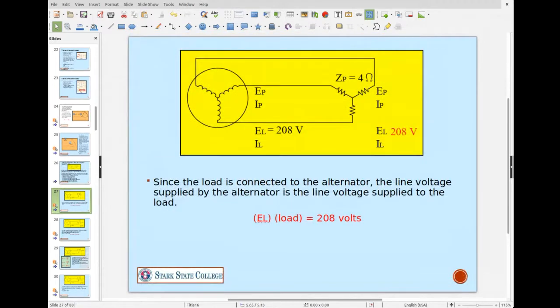All right, so one thing that you're going to see here is this 208 volts. If you were to look, we know like in our house or whatever, we have 120 volts RMS. Okay, if you were to multiply that times this square root of 3, that gives you this 208 volts.